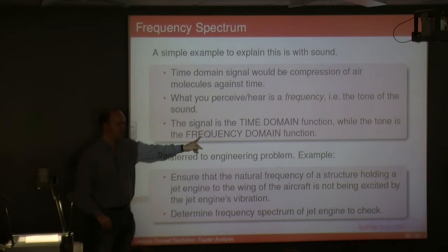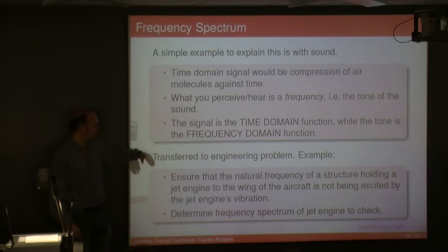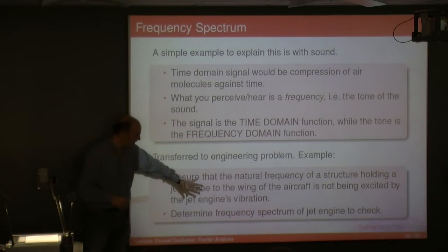But you also look at it in terms of frequency, which will give you the strength of the response, and that tells you an awful lot about the control system. But like I said, it's got engineering applications in terms of vibration as well. If you want to test a structure, to make sure that whatever excitation force it's going to experience is not going to hit resonance, then you can do this.